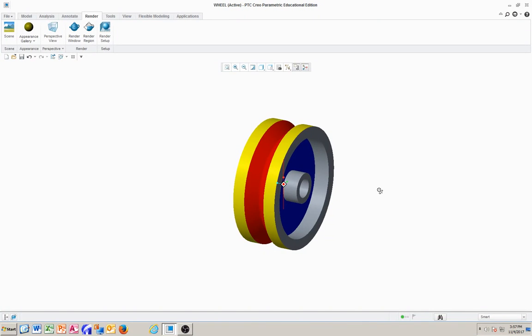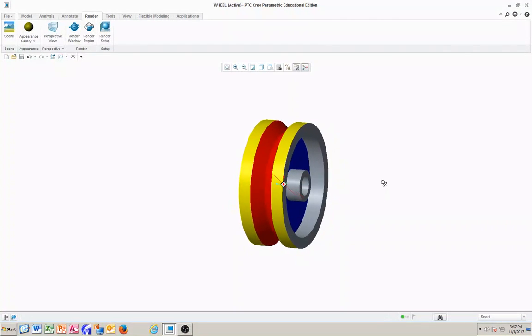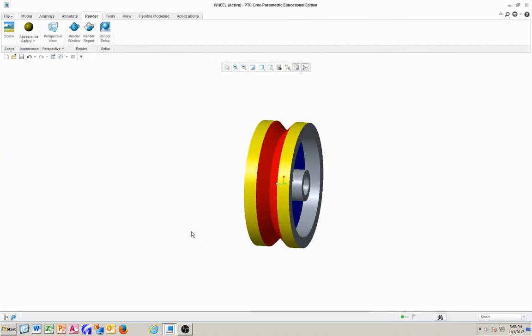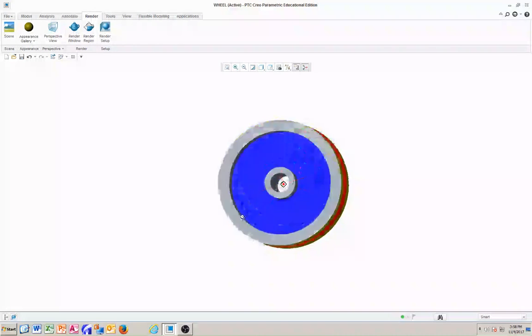One thing I want you to remember, you have done project 1, you had a bushing, and you have a bushing for project 2. You have to be careful when you do the assembly. Try to erase the memory of project 1, otherwise it will bring the previous bushing and place it in here, which is not a good idea.